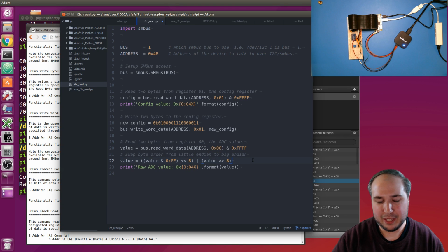Now, if I just talk to the device at a byte level and ignore sending words of data, then I don't have to care so much about the endian order. If I want to look at a 16-bit value, I still have to take those 2 bytes and put them together in some way, so I do need to know the endianness there. But it's just something to be aware of and to be very careful about.